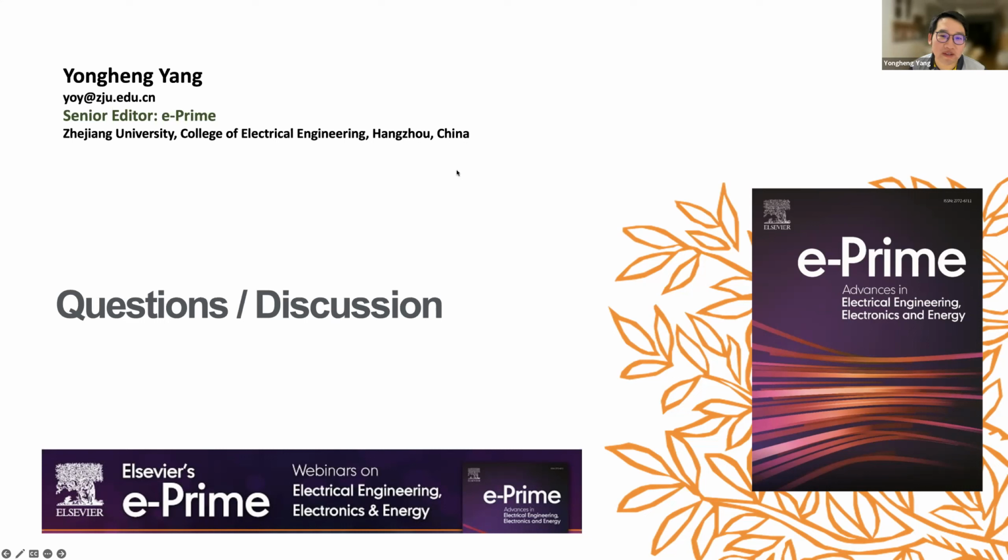these advanced devices like silicon carbide devices and wide bandgap devices, you have a higher switching frequency, then you have a higher power density, and the reliability can also be improved because such devices are usually claimed to have a higher reliability compared to the silicon-based devices.